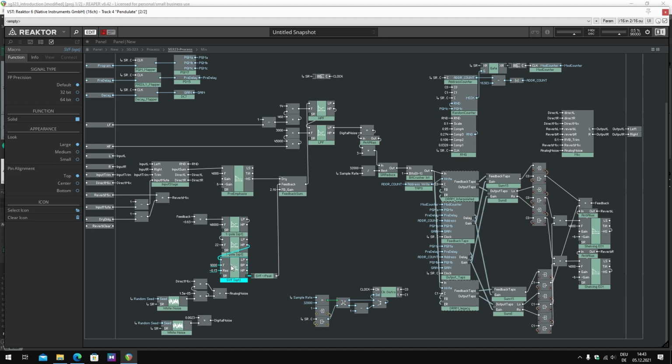And this is a state variable filter, which usually only has low pass, band pass, and high pass outputs, but there's a pickup macro to convert the output to a peaking or shelving, peak filter, bell filter. And then we sum the feedback together with the input signal, and the feedback will have a gain of 2.16 applied.